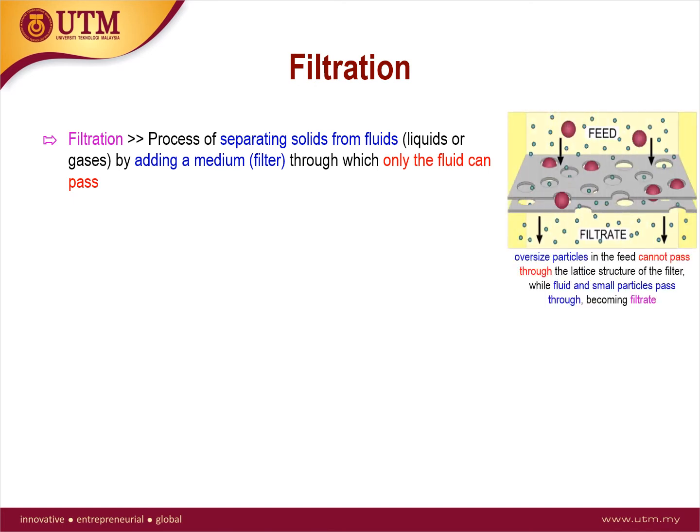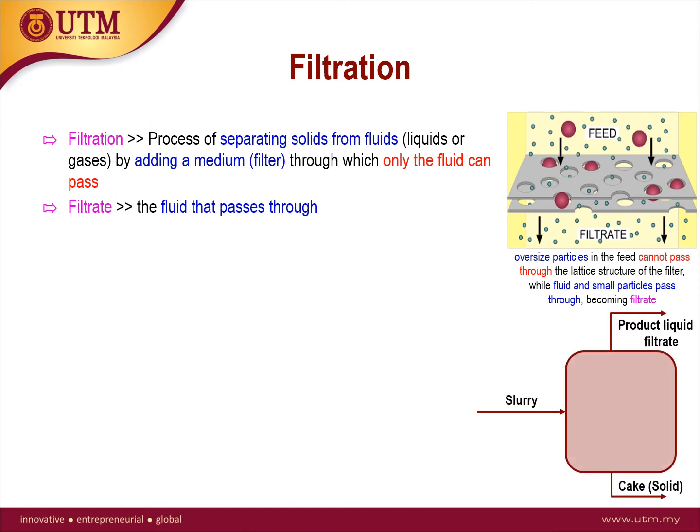Solid particles that cannot pass through the filter medium are described as oversized, and the fluid that passes through is called the filtrate. The oversized particles may form a filter cake on top of the filter and may also block the filter lattice, preventing the fluid phase from crossing the filter, known as blinding.